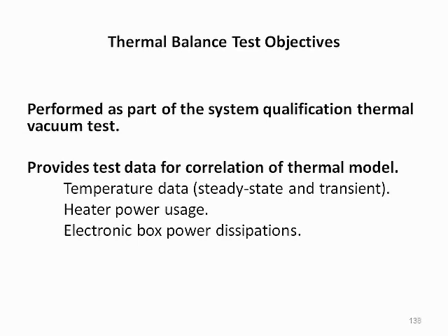Next, we turn our attention to spacecraft level thermal balance test. Spacecraft thermal balance testing is usually performed as part of the system qualification or proto-qualification thermal vacuum test. The primary objectives are to obtain test data for correlation to the thermal math model and to verify the thermal design. Both steady state and transient temperatures, heater power usage, and electronic box power dissipations are recorded to aid in math model correlation.